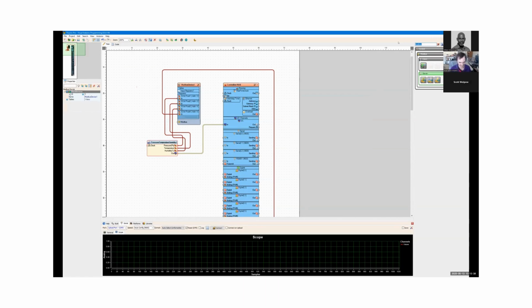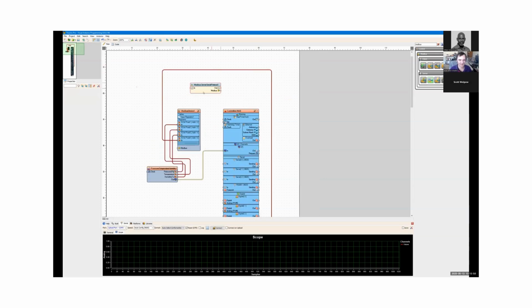The next thing we need to do is add a protocol, and we will use serial communication for the first example. So since this is a server, we need a server Modbus protocol, and we'll use the RS-485 port because RS-485 is industrial communication physical layer, which uses just twisted pair.